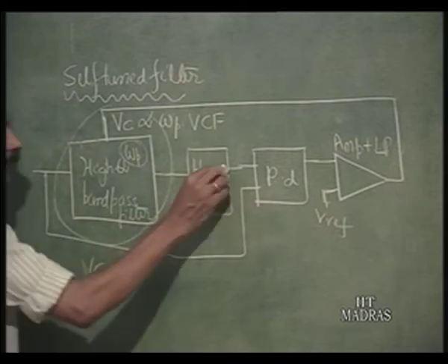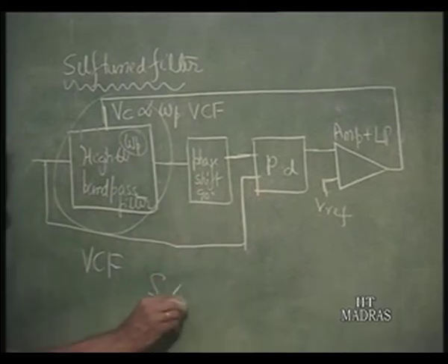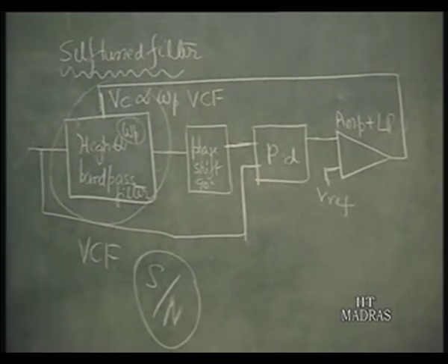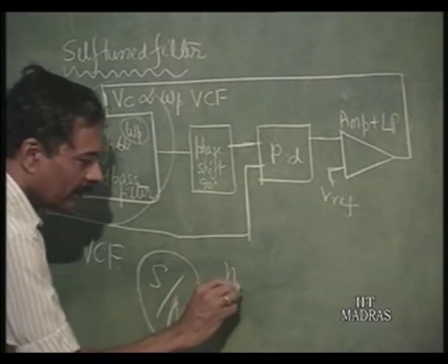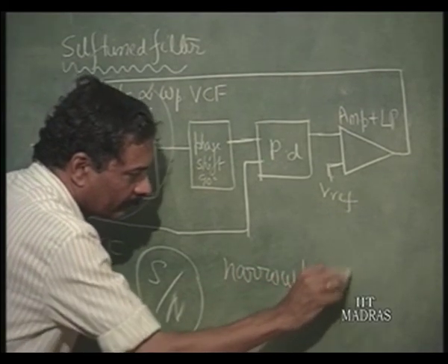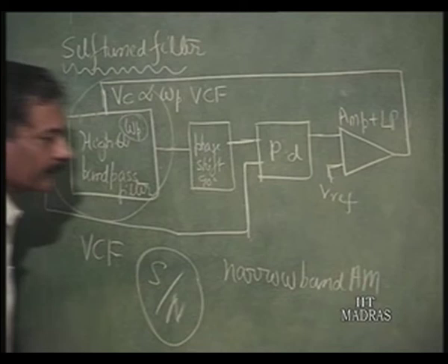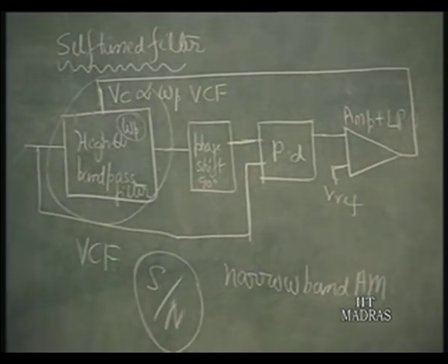So this kind of self tuned concept is used whenever signal to noise ratio improvement has to occur drastically. This is applicable for narrow band AM signals, so that the high Q filter can be used here.